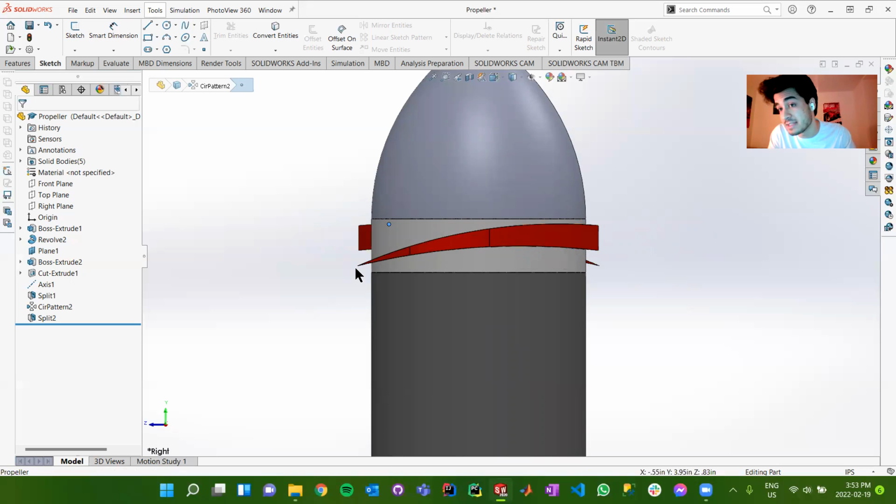Or very, very easy to sketch, I should say. So what we have here is one proper profile, two different arcs with different radii, and one straight line connecting the two. So what we can do is we could say, okay, for the first stage, we're going to take this sketch and we're going to extrude it out towards us along the x-axis, right?